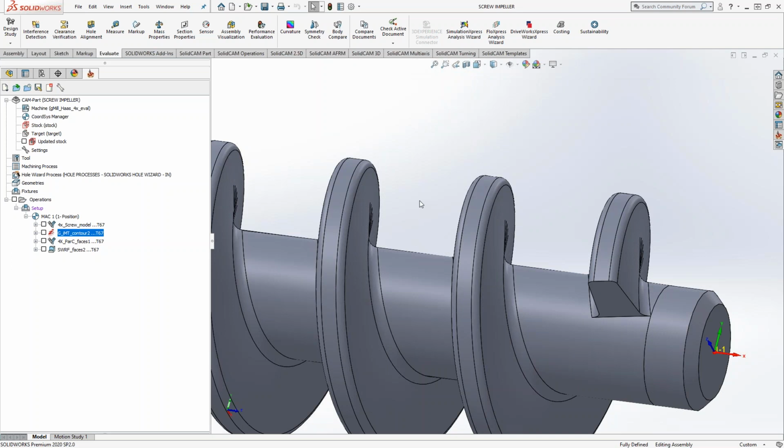I think the only places you can't is probably toolbox cycles and things like Contour 3D. Contour 3D itself is already three-dimensional. I don't think there's a way to do a fourth axis on that. But in that case, you probably wouldn't be doing that anyway, because if you're doing a wrapped, it already is moving enough that you can probably achieve whatever feature you're trying to get with the Contour 3D.